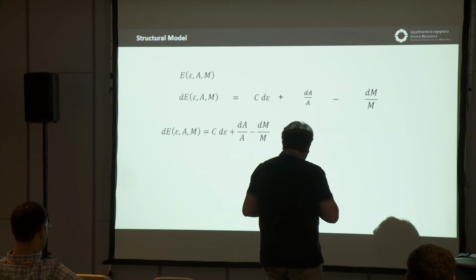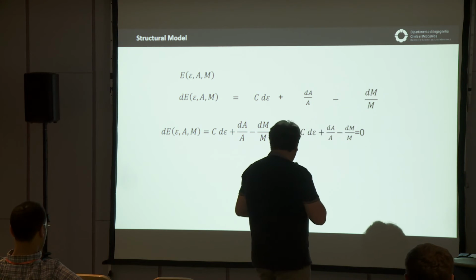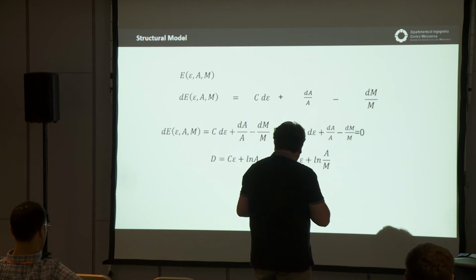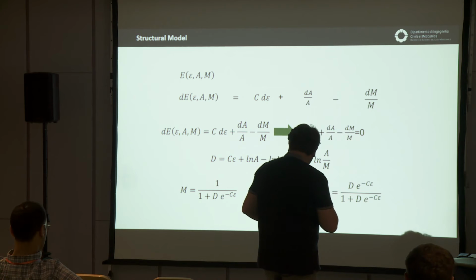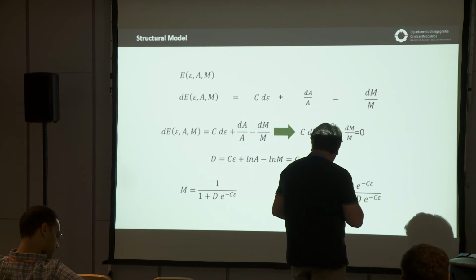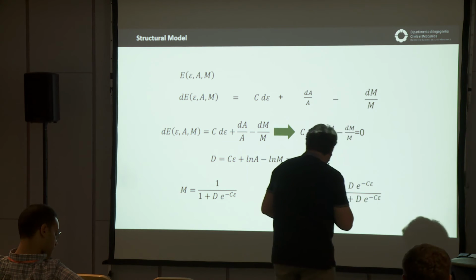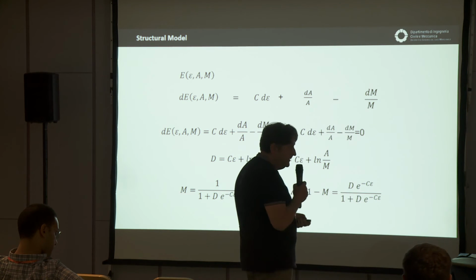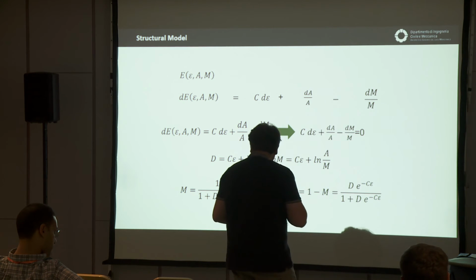At equilibrium, this equation must be 0. And integrating at the equilibrium state, we have this relation, where it's trivial to obtain a very easy to use relationship of the martensite quantity as a function of epsilon, and the austenite one as the complement to 1 of the volume fraction.